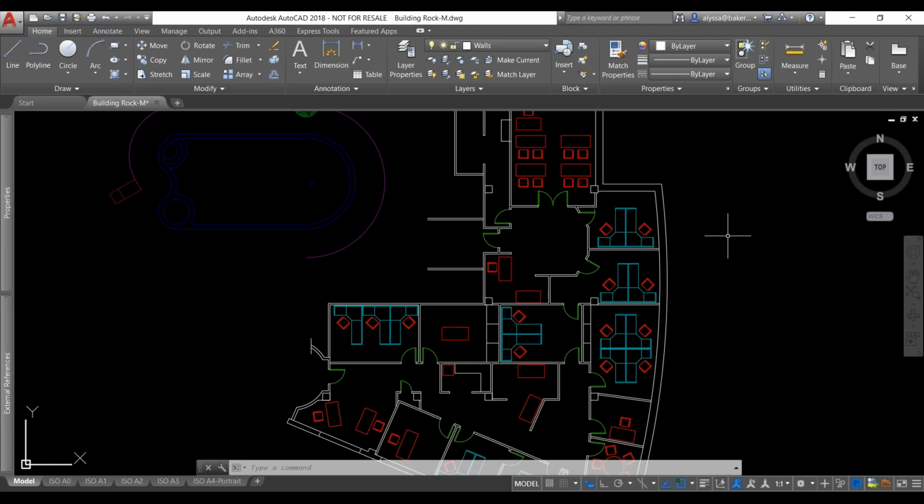Each value or number for a command defines certain settings. For example, when we put in select off screen, a value of 0 meant that the selection deselected on zoom, or if it was 1, it kept the selection. Okay, 2 is so and so, etc. So that is a system variable.